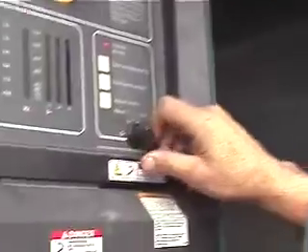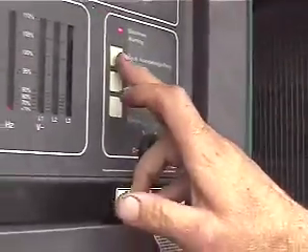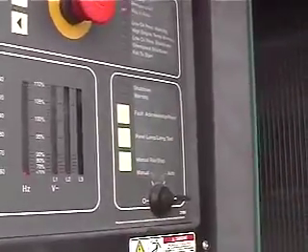Number one question I get on a phone call is somebody has hit the E-stop, the generator won't start. I have them go through what I just told you. They pull the E-stop back out, but then they don't reset it. So to reset it, you have to take this to the 0 position, push the fault acknowledge reset, and then it clears the fault. That is the number one question I get called about.